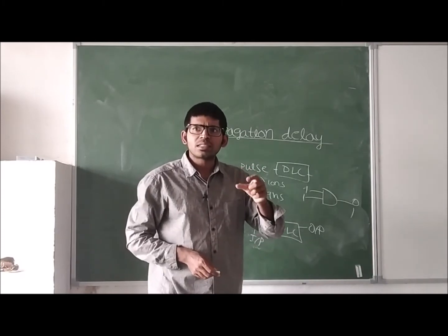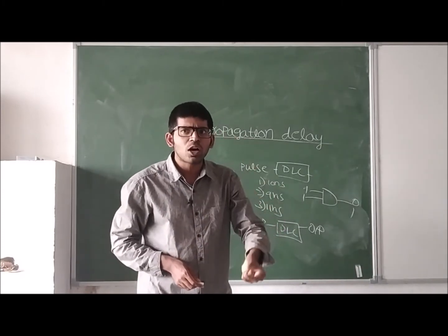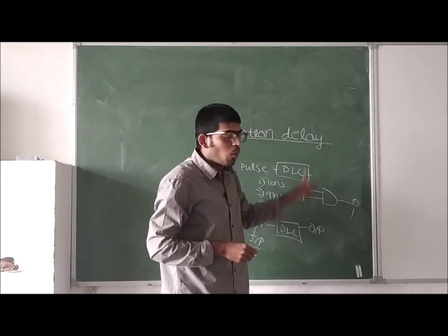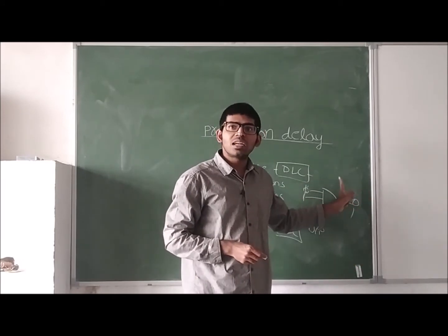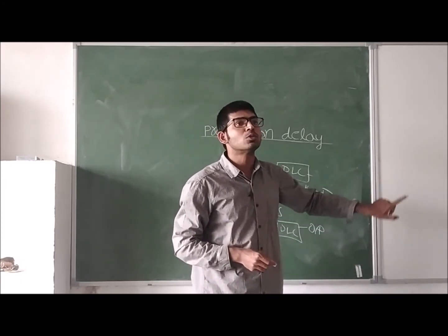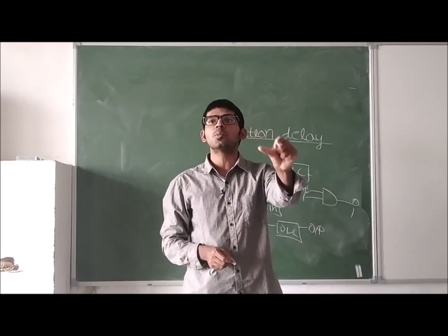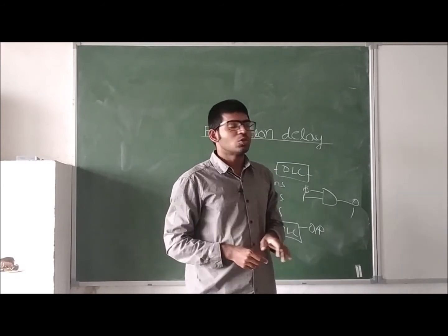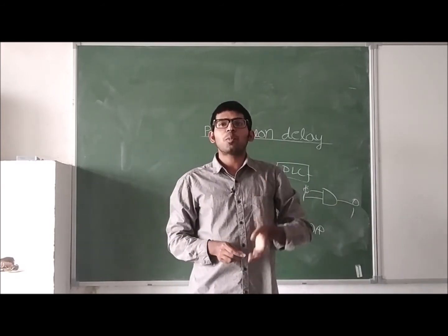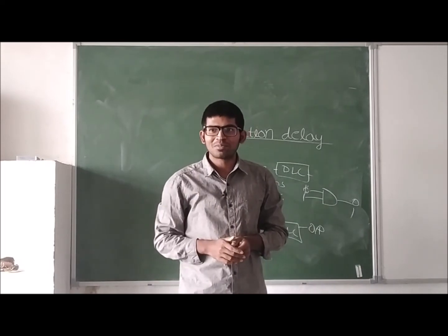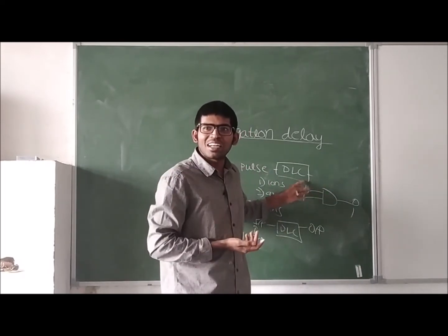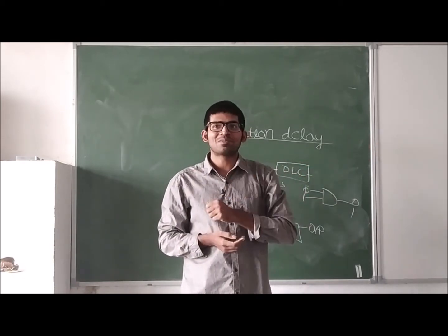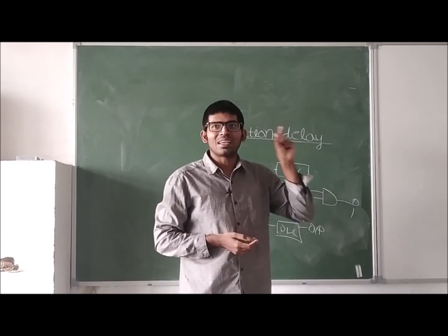Now we say that fraction of time, when I changed the input from 0 to 1, is the time taken by this digital logic circuit to change the output from 0 to 1. That time is called the propagation delay. Generally we hear of wave propagation, where a wave propagates. Similarly, it is the mean time taken by the pulse to travel through the IC.